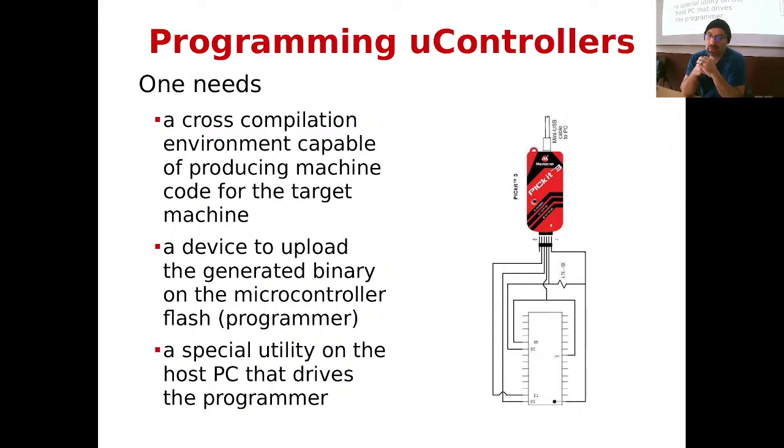We require a device to upload the software to the microcontroller, if this device is not integrated in the board, as in the case of the Arduino board. And then we need a special utility that talks with this device or with this piece of software, which is called bootloader, for taking our binary that is existing on our machine and uploading it into the flash memory of the microcontroller, right?